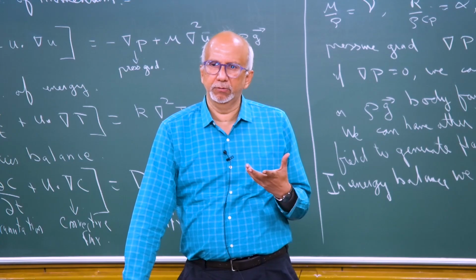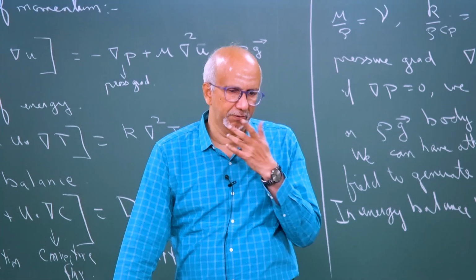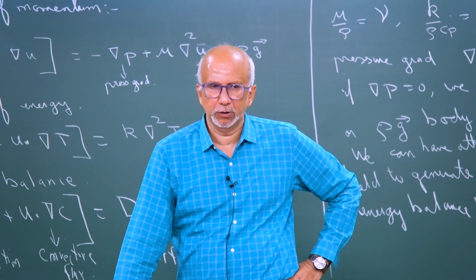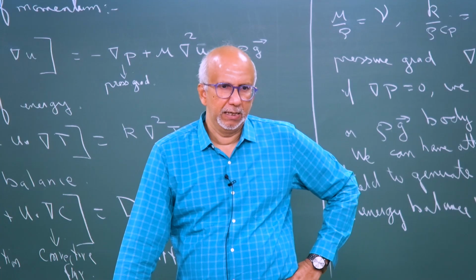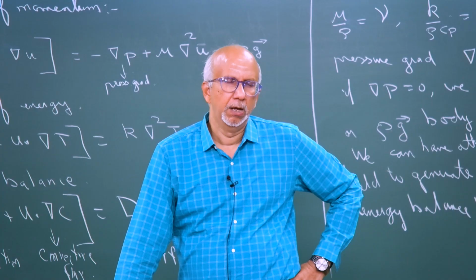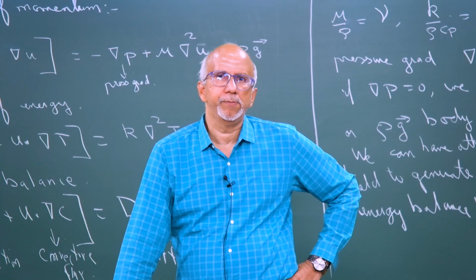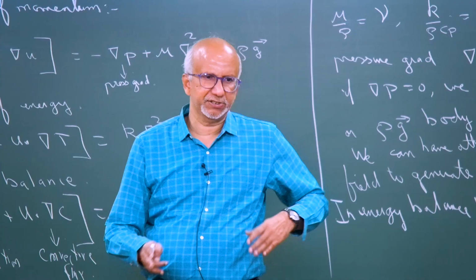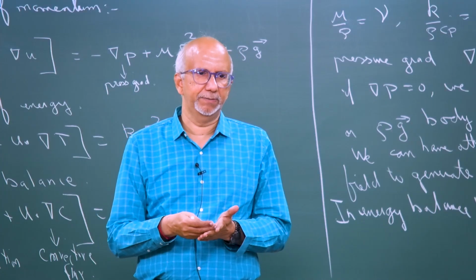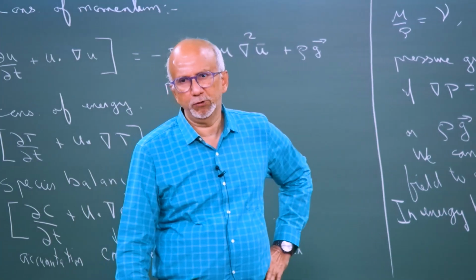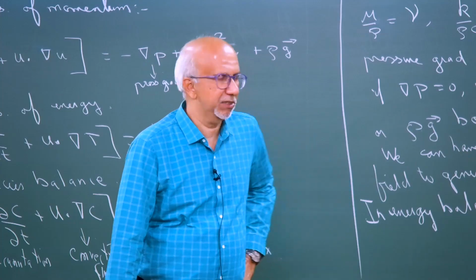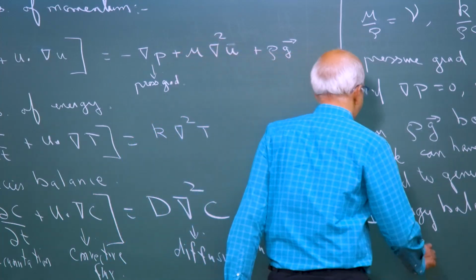Another thing which is frequently encountered is viscous dissipation. So, viscosity, remember, is something like friction, it prevents movement, right. So, you have friction when two layers are moving side by side, and heat is generated. Similarly, in a fluid flow, because of viscosity you can have heat generation. Okay. So, this is usually added here. So, heat, viscous dissipation.